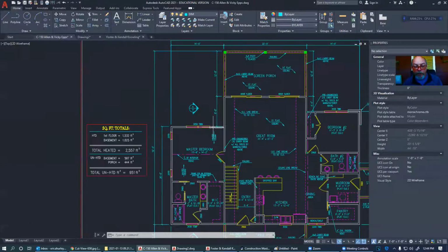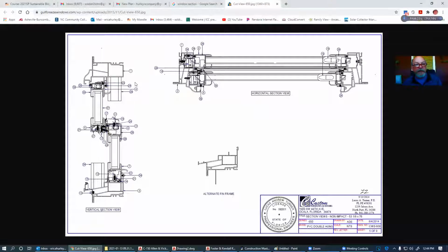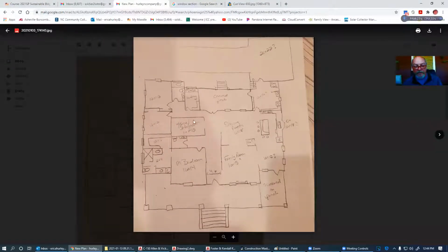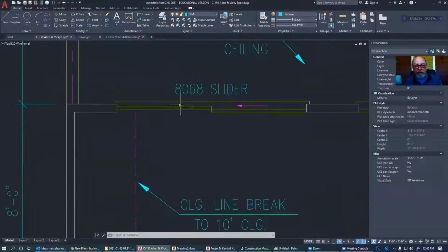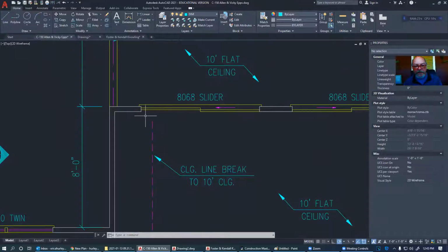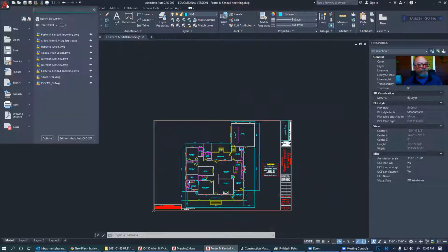When you measure your windows, the only thing we're worried about right now is the plan. So when we're thinking about doing a sketch of a plan, definitely don't give me this one line stuff here. I want you to look at this, already have your wall thicknesses in, how big of a window you're going to be. Go ahead and put that in feet and inches, much like what I've done here. So we've got a door. This particular door is a huge door, 8 feet this way and 6'8" up and down. Most all of your doors are going to be 6'8", except for crazy houses like this. Let's see. Nope, wrong one. This house.